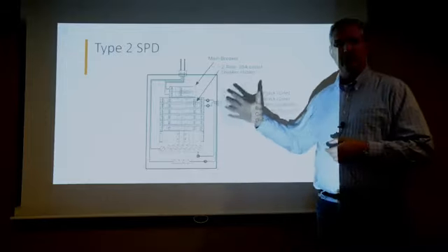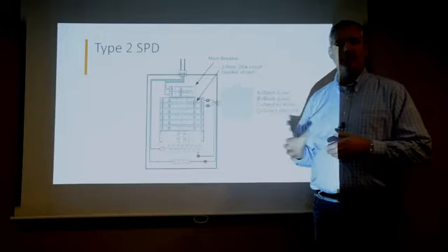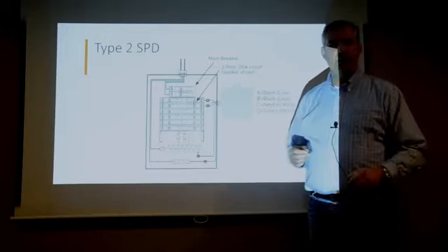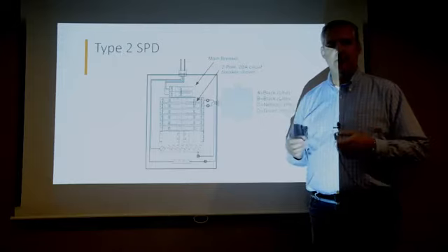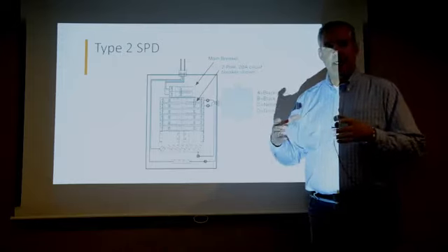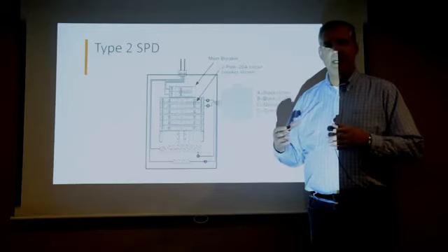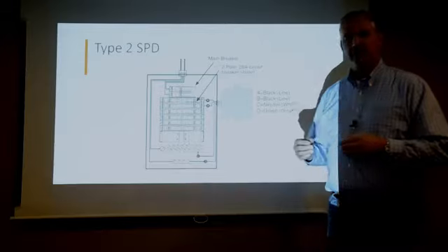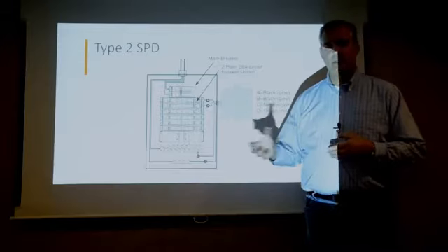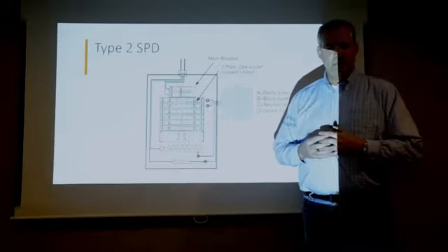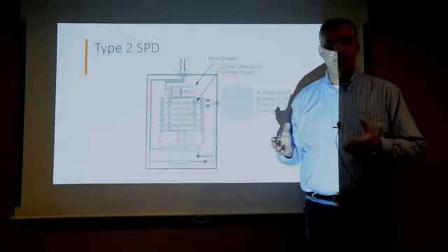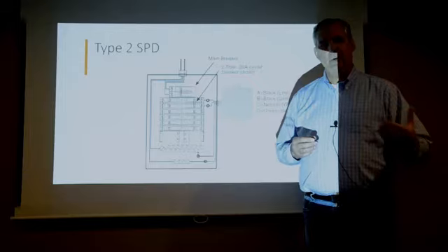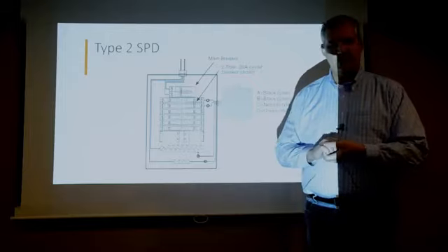Now this prevents anything from outside coming in, and then there is your type 3 surge protector, which is basically a power strip looking device, but there are many variations, so you have to be careful of which one you select for the use that you have. So if it's a computer workstation, or anything that's expensive, you want robust surge protectors protecting those devices.